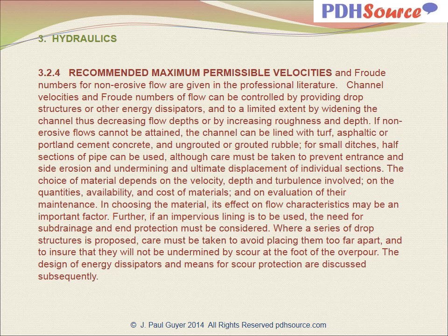Where a series of drop structures is proposed, care must be taken to avoid placing them too far apart and to ensure that they will not be undermined by scour at the foot of the outpour. The design of energy dissipators and means for scour protection are equally important.